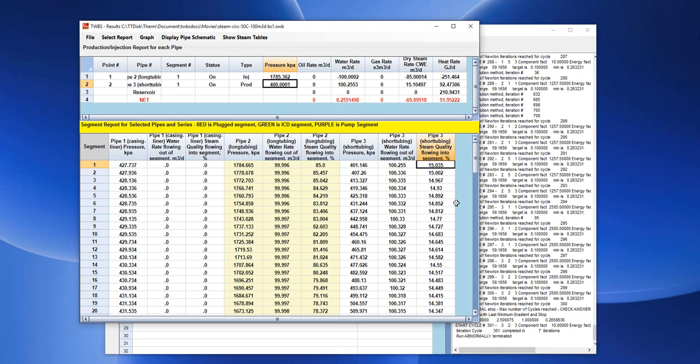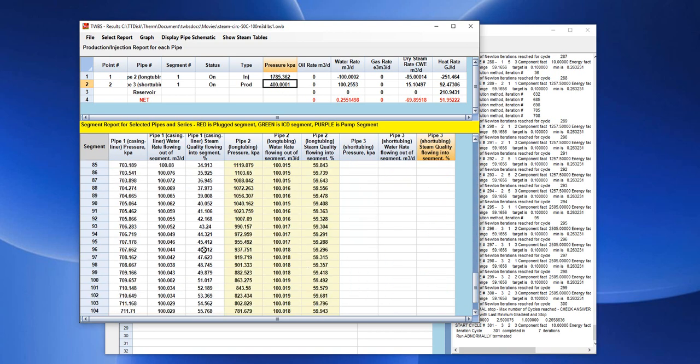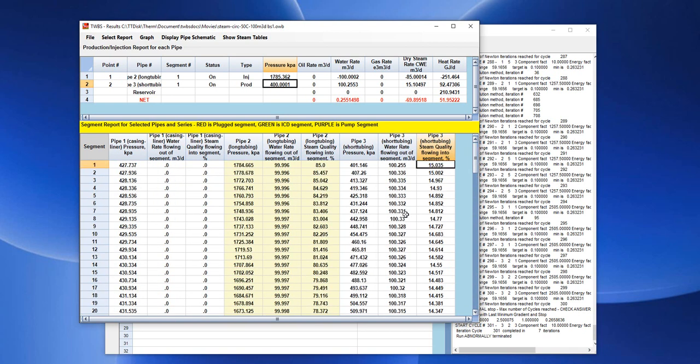So this has cooled down, but it's still a steam path all the way from the injectors, long tubing, down to the toe and back along the annulus and back up the short tubing. It's still a steam path, so our pressure difference is not that dramatic yet. So we're going to now take the same case and do another baby step. In this baby step, we'll cool down the reservoir to the 15° C, say, initial condition, and then we will see how we can run it.